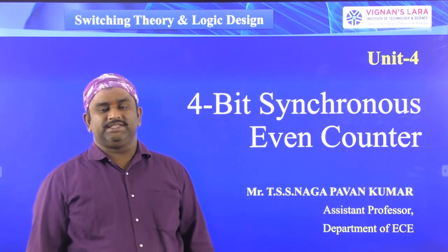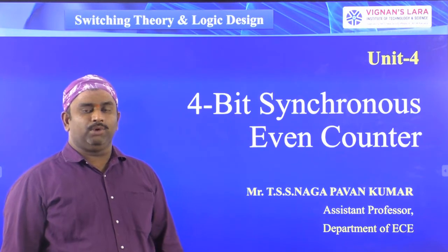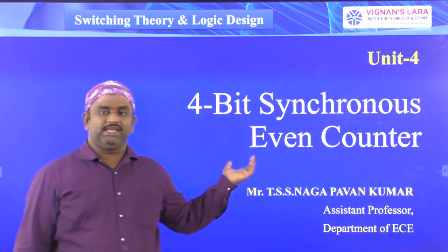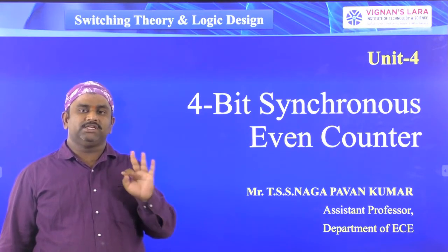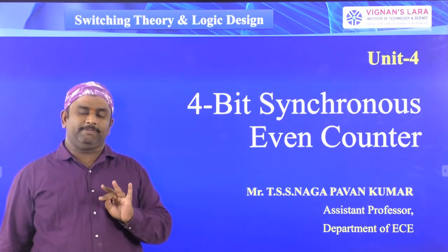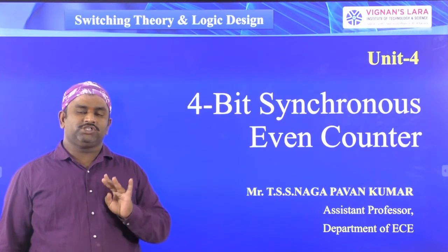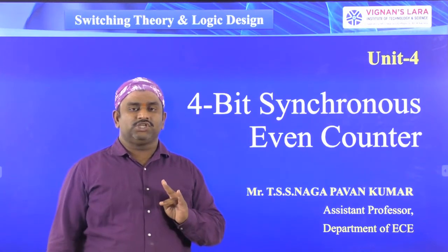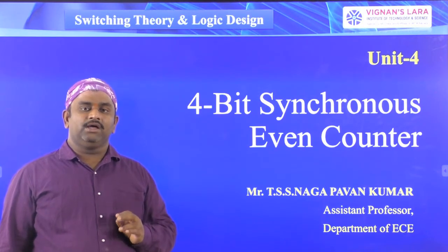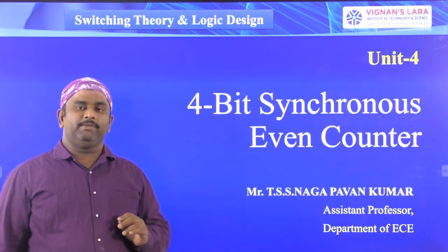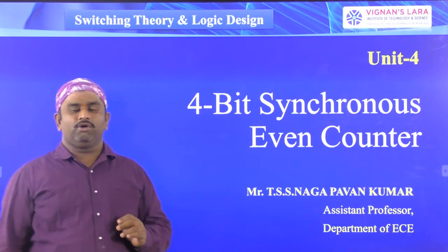Before going to the design, let us remember one thing. The synchronous counter design has a total of 4 steps. The first step is the state diagram. The second step is the state table. The third step is the reduction of the state table outputs. And the fourth step is designing the logic diagram by using the minimized expressions which you got from step 3.